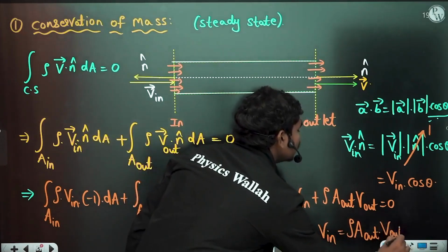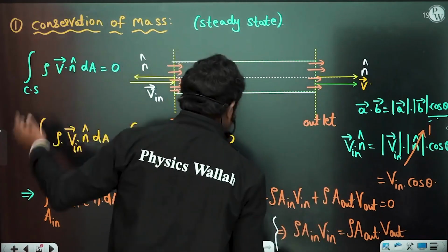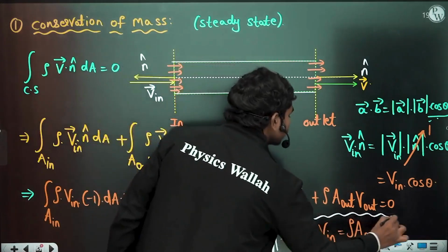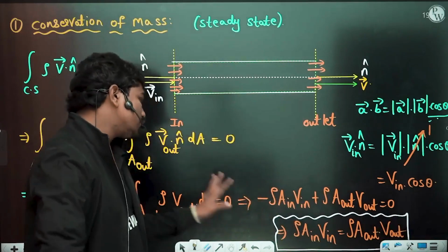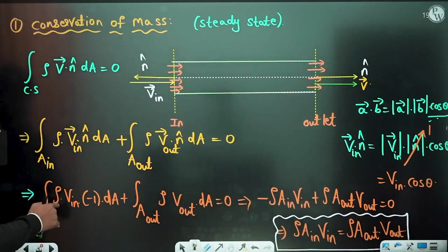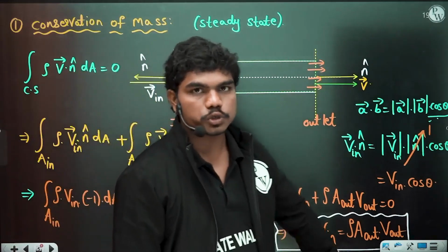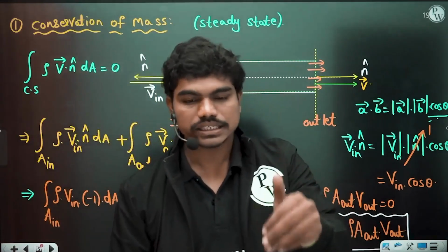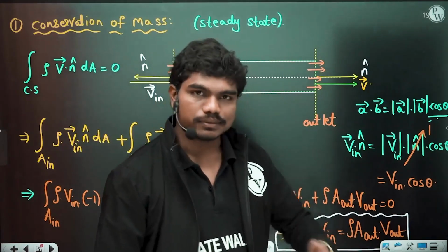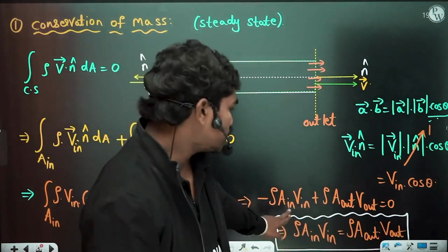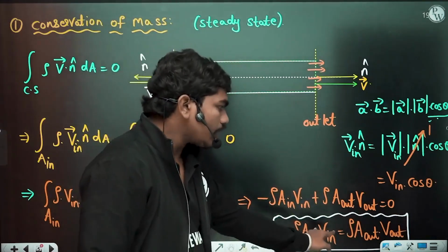Correct. This is what you can see here, and this is told as your continuity equation. This is how, in simple terms, you normally write it at two sections in the flow. If you don't assume that the density is constant, then rho in and rho out are also written, so rho 1 A1 V1 is equal to rho 2 A2 V2. Normally in fluid mechanics in our course we will take density as constant, so we will write that separately. In thermodynamics, you will get this as rho 1 A1 V1 because gases behave as compressible fluids there, so that's why this is the equation.